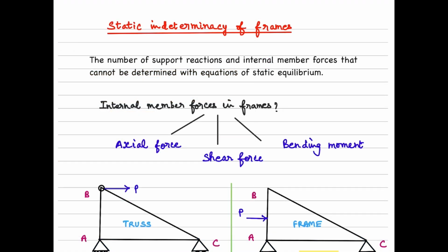Let's begin the exploration on static indeterminacy of frames. We are now already familiar with what is meant by static indeterminacy. That is the number of support reactions and internal member forces that are in excess of the number of static equilibrium equations.